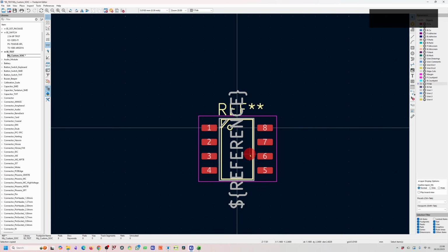So when you are doing your outputs for PCBWay, you can just basically go to print, and you would print the edge layer and the fabrication layer, and it would give you your reference designator with this, and it would give you this outline over here as well for your component, and you'd get a very neat looking assembly drawing for your PCB showing where the component location is.